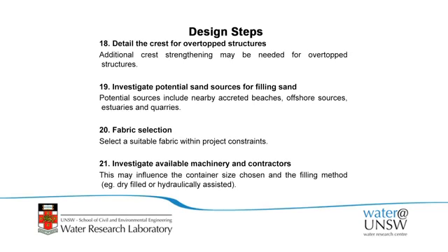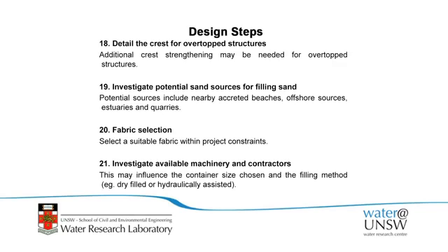Also investigate the available machinery for constructing the works. Again, if you're anywhere on the mainland of Australia between Noosa and Hobart, or pretty much anywhere on the mainland Australian coast, there's going to be available machinery, particularly if you're near any capital cities or major regional centres. If you're proposing to do something like this on Lord Howe Island or King Island or Pitcairn Island, certainly there's not going to necessarily be the machinery you want there, which may influence the container size, because the bigger containers need different machinery and bigger machinery and specialised plant to construct them. So think about what machinery you might have to build it, and that may push it down to the 0.75 cubic metre containers versus the 2.5s.